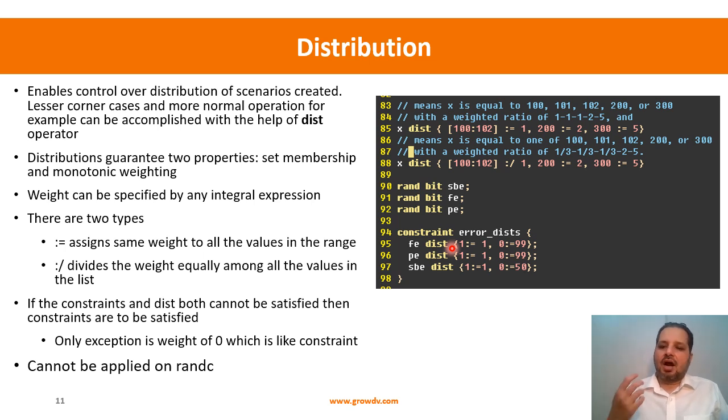So that is why you start off with the normal operation, give higher probability to that, and give lower probability to error injection, so that you're still able to see a few cases. As the project progresses, if you have more time, you can include the low probability cases, you can make it high probability, you can make it low probability, and focus on a different area. So that's how the distribution constructs help you focus the randomization to a specific area of priority where you are trying to do risk reduction.